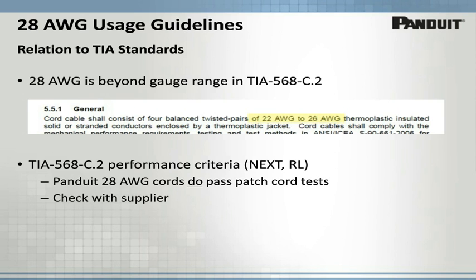And this is a great question, I appreciate whoever in the audience asked it, because it is one of the key things that most people want to know when they look to use 28-gauge cabling systems. And when they find that it's completely performance compliant, subject to the length limits that we talked about, this is where people get really excited, because basically it is that equation or that statement that we talked about. They're willing to give up 4% or maybe 7% in the overall channel length to get this massive, over 100% increase in pathway capacities. Other things that we didn't even spend so much time on: increased flexibility of the cabling, just the overall ease of management of the cabling. So I hope that addresses that question, Patrick.